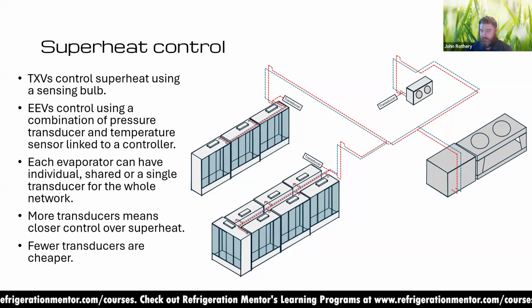So say, for instance, a manufacturer, Carel, they've been around for a while now. It's just knowing and interpreting the parameters that you need. It's definitely overwhelming, without a doubt. One of the issues on, say, the Carel front end is when you get a graph and you switch between various readings, you have to check the scales, because you can set it to auto scale, which may make things not align.